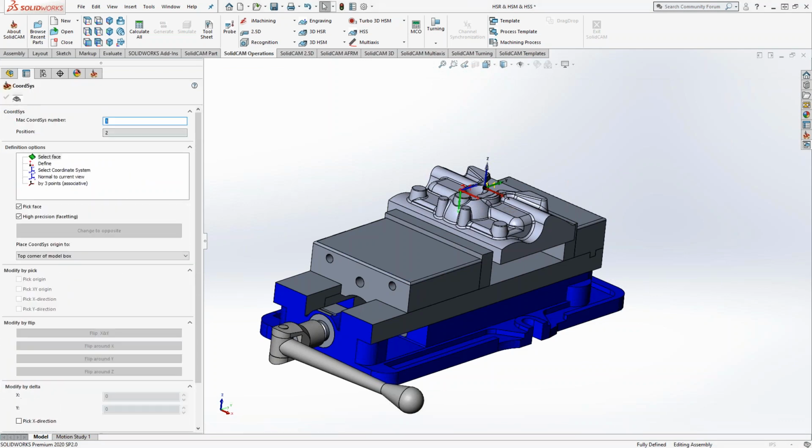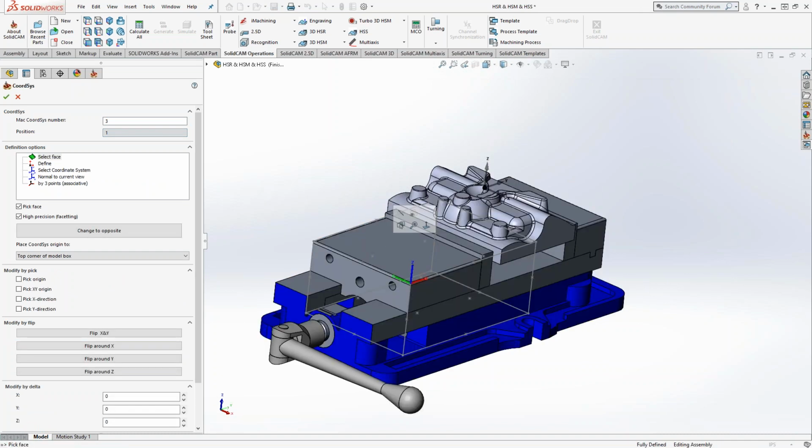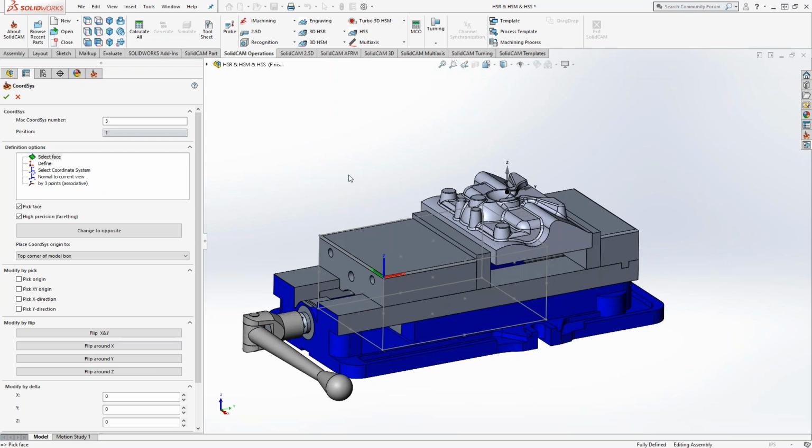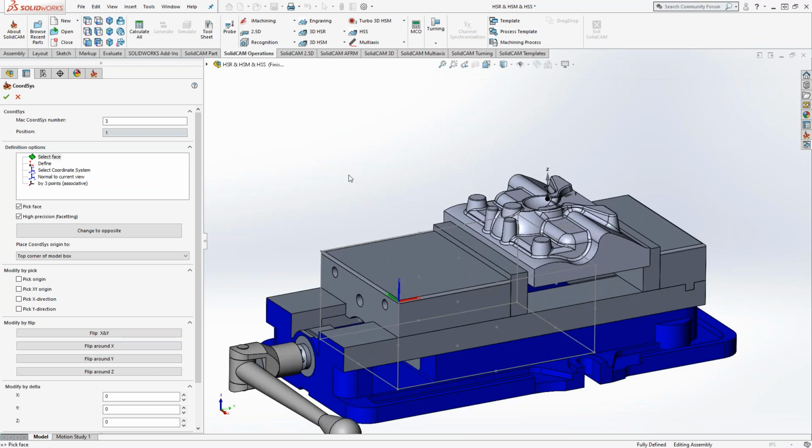And this makes it really handy, like what Mark's saying, if you have nowhere to probe. I know at my previous job, we had a probe, we would stick in dowel pins or do dowel holes. So the probe could go in there, probe it for the X, Y, and Z for that hole, even though that part wasn't even near that. So definitely use that to your advantage as well. Absolutely. Use what you have in front of you, basically.